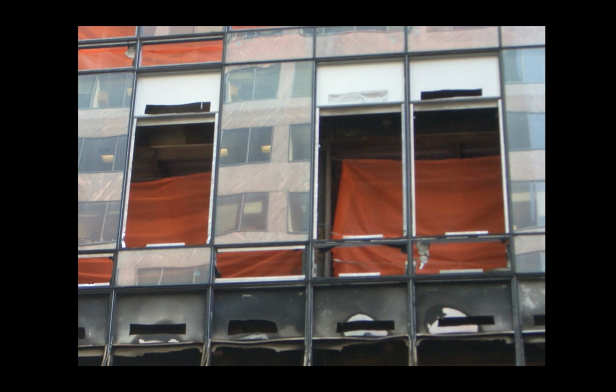Alright, so you see some of the safety within, even though mullions are in place in many of the panels. You can see there's still a couple panels that need to be placed. So what do we do? We have to put in some kind of fall protection or netting in those vacated areas and maintain that until we have the structure sealed.